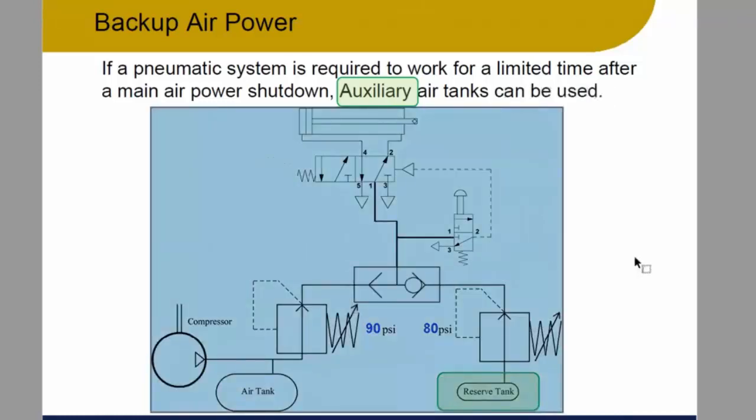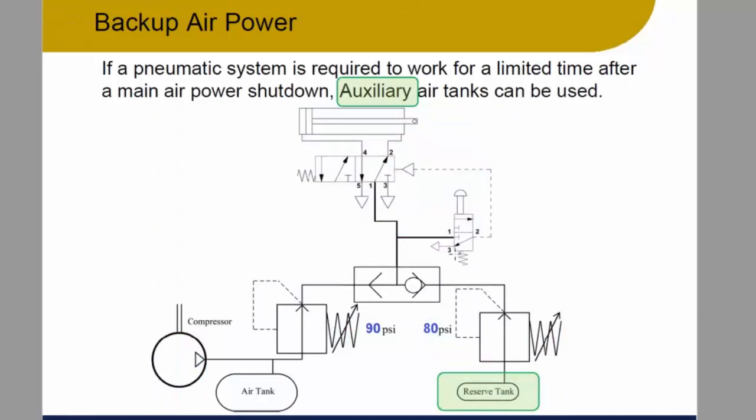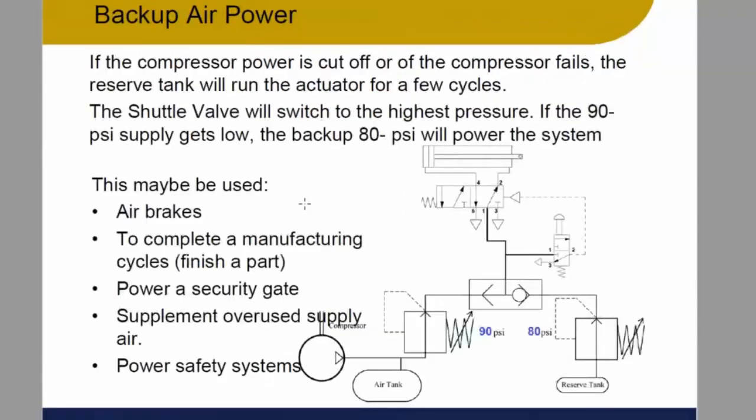The other thing that's really cool is we also have AND gates, maybe not the right word, but an AND valve. The reason I said gates is because some of you may know the term gate, an OR gate or an AND gate from electronics. In pneumatics, we have OR and AND valves. So we can add logic with this, although in this situation, this shuttle valve is used for a safety application for fail-safe design. We have another situation over here.